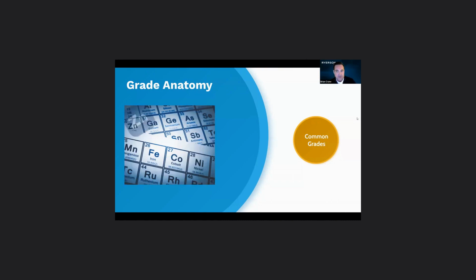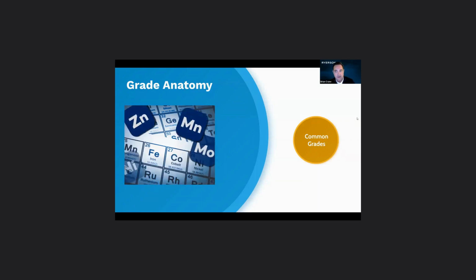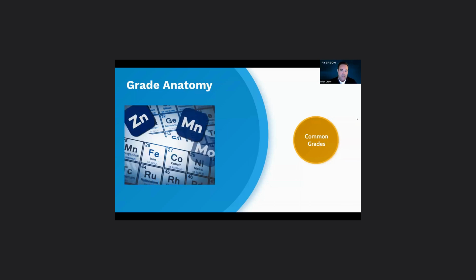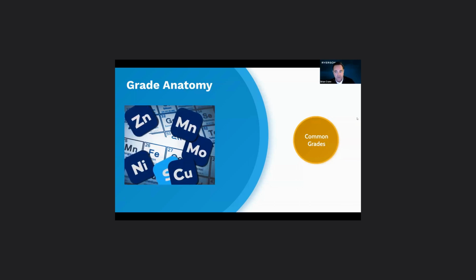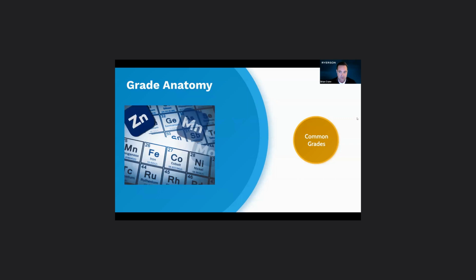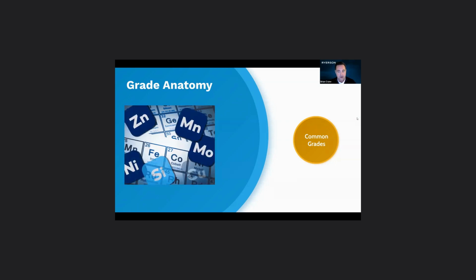One more thing on plate products that I'd like to introduce you to is that plate products are broken down into two segments, as rolled and heat treated. As rolled is like hot rolled, a product straight off the mill, produced at the desired grade for your end use. Heat treat plate is where the as rolled product is reheated in a furnace and either left to cool in the air, which is called normalizing, or dunked in a bath of oil or water. This process is called quench and temper. These processes are designed to refine grain structure or increase the strength or hardness of the plate, all dependent on the end use.